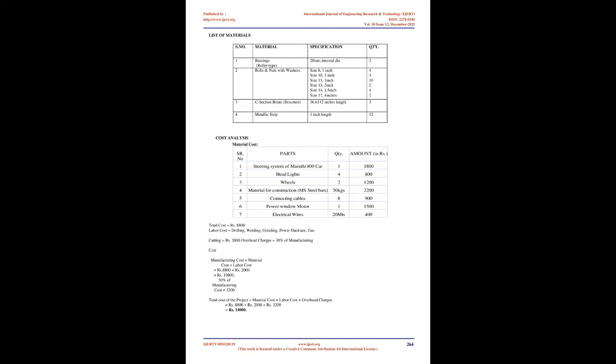Electrical system. Automotive battery. An automotive battery is a type of rechargeable battery that supplies electric energy to an automobile. Usually this refers to an SLI battery, starting, lighting, and ignition, to power the starter, the lights, and the ignition system of a vehicle's engine. Automotive SLI batteries are usually lead-acid type, and are made of 6 galvanic cells in series to provide a 12-volt system. Each cell provides 2.1 volts for a total of 12.6 volts at full charge.